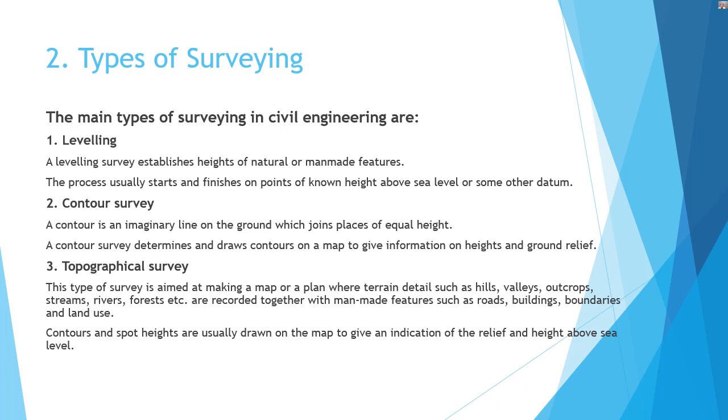The contour survey. You will need the contour survey because you want to know the features of the topography of the land. You know the low point, the high point, where you want to build a road or a new building. You need to know whether you have to do grading. It means you have to cut or fill, and that is the earthwork you have to do to make sure that you have a flat level where you can build the road or the building.